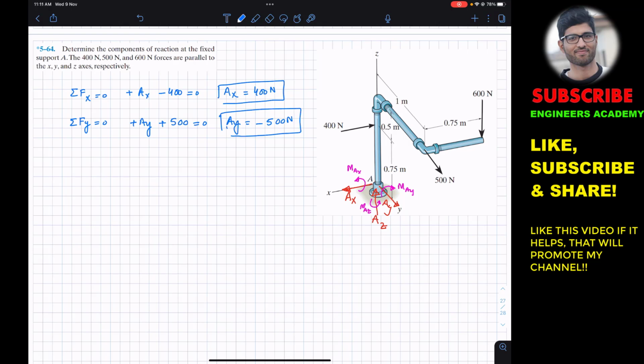Similarly, if we apply the summation of forces along the Z axis, that must be equal to 0. In the Z direction, we have this AZ in the positive Z, so I will write plus AZ. And this external force is acting in the negative Z. This is 600 Newtons, so we will write minus 600 and this is equal to 0, and from this we can say that AZ is equal to 600 Newtons. So now we have determined the force reactions AX, AY and AZ at point A.